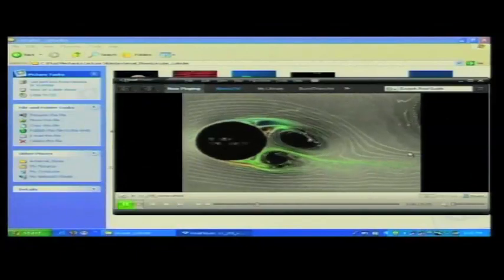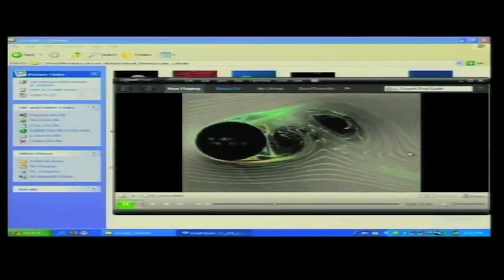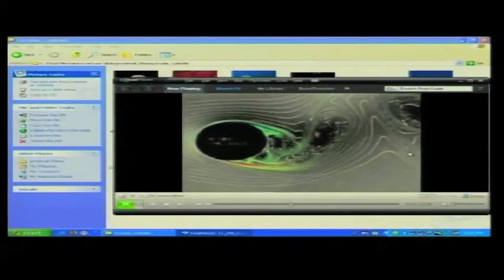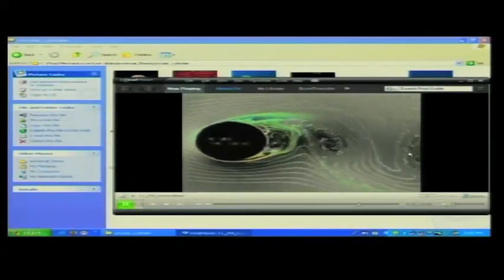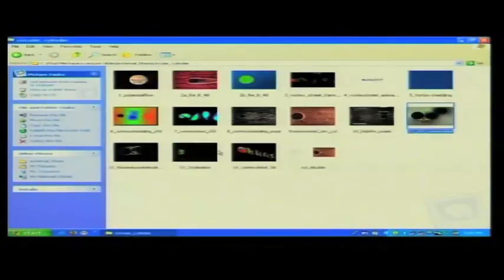This is a computational way of generating the similar type of behavior, and you can see from this example clearly that these vortices are as if rolling upwards and downwards like that, and that creates an alternating sort of frequency in the flow. So the flow itself is inducing some nature of rotationality or some nature of frequency in the system, and because of this sort of transience in the flow, the cylinder may itself start oscillating. So this is called flow induced vibration of the cylinder.